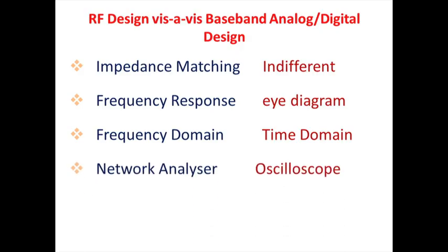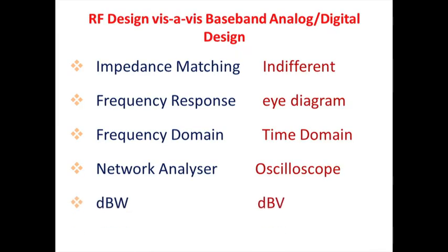Then to see any device, since you know that in low frequency work we look at oscilloscopes to look at a waveform, but at higher frequency we need to see how the behavior changes with frequency, and we also need a wave sort of picture, that means whether there is a wave going in the forward direction or getting reflected and coming in the backward direction. So, that is not available from an oscilloscope. That is why the basic instrument used at RF frequency is the network analyzer. That is why we will see the network analyzer also at the end of this series of lectures or this course.